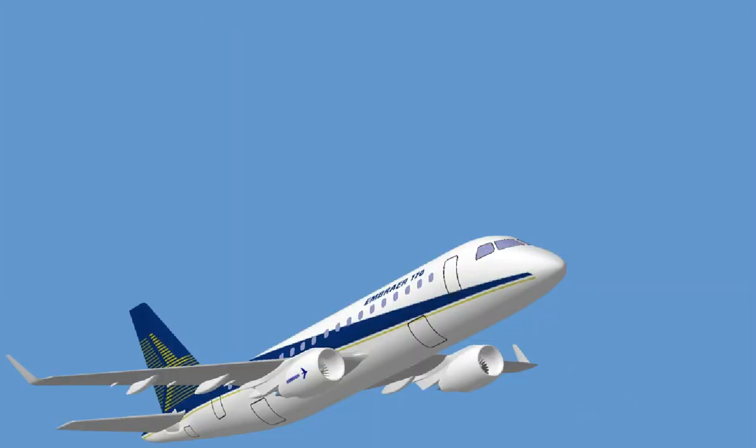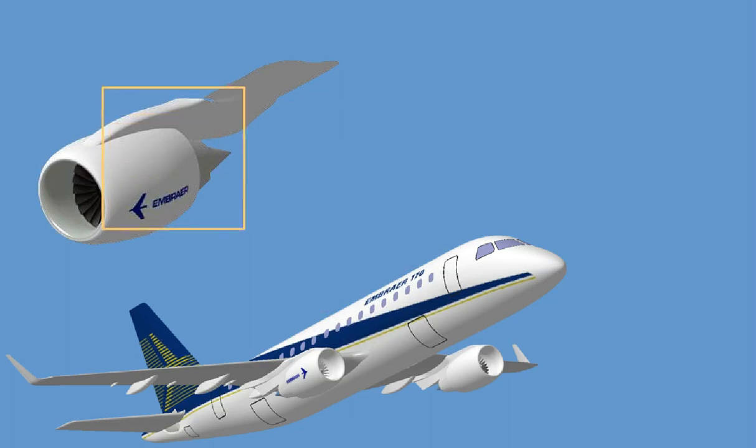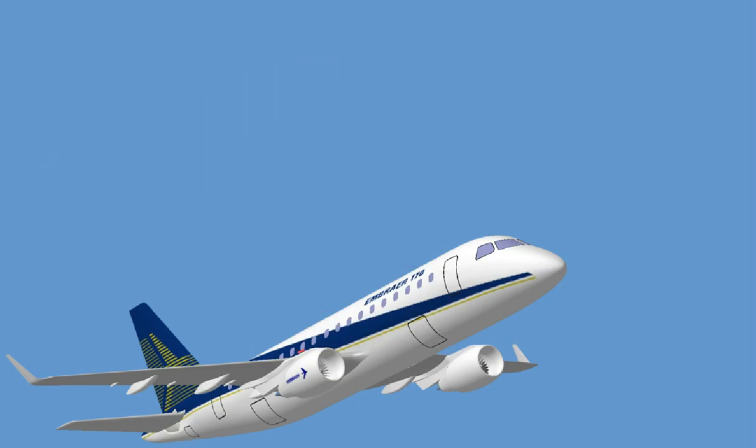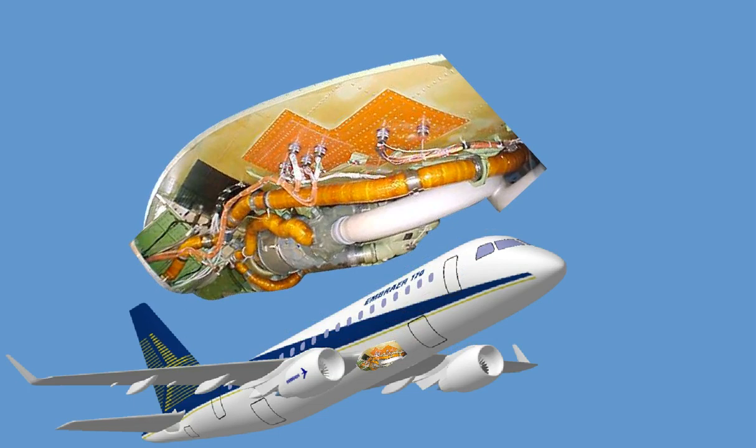The pneumatic bleed lines running from the engine bleed ports and ram air inlets through the pylon enter the wing leading edges and run toward the packs. The ECS is installed at non-pressurized location under the midsection of the fuselage, under the wing-to-wing fairing. The pneumatic bleed lines are installed in this area. Only conditioned air will enter the pressurized cabin.